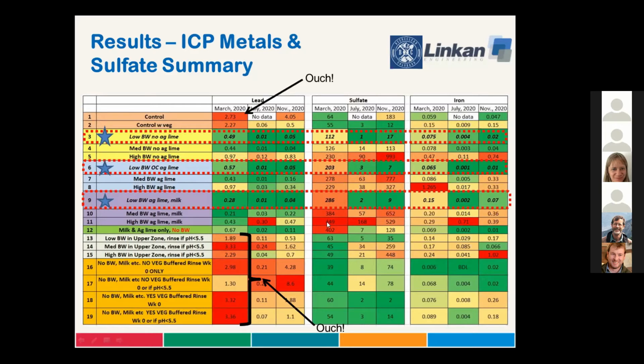So in the green cells, these are the ones that produce green leachate. Again, this is probably ferrous iron. And only number 15 with the high brewery waste exhibited really high iron, but number 5 leachate was a weak tan color in the final sampling event. The control leachate always had iron and showed elevated lead throughout the test.